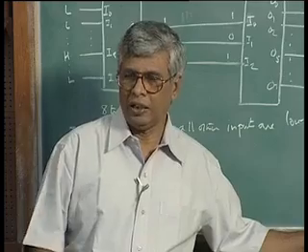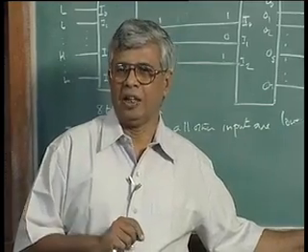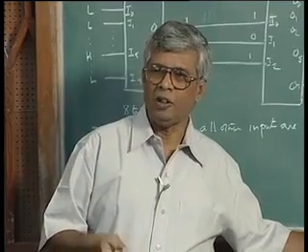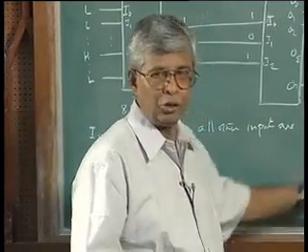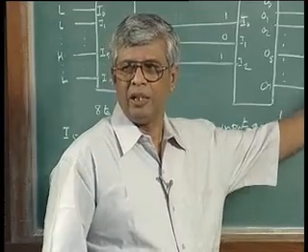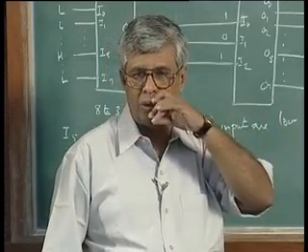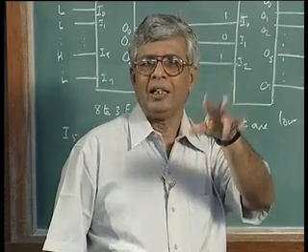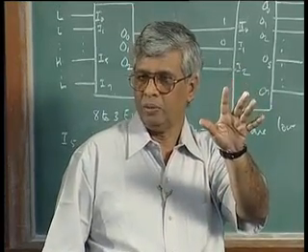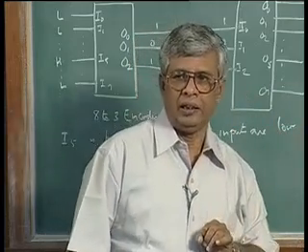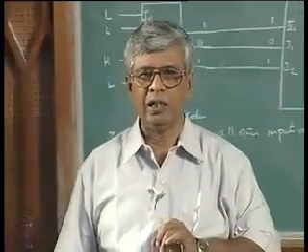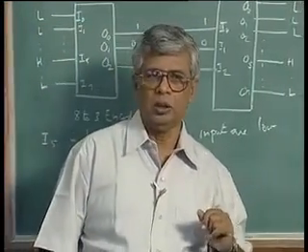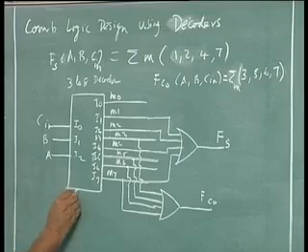One of the things is there is always an enable signal in all of these, whether it is a decoder, an encoder or a multiplexer. There will always be a signal called the enable signal. I will introduce it here because it is the same in many ICs, but I thought sometime I should tell you all these things before you get out of this course. Like preset and clear and extra signals in flip-flops. For a logical design or a simple analysis understanding of the flip-flop, you do not need to know it, but then I introduce it. Likewise, here I want to introduce a signal called the enable signal.